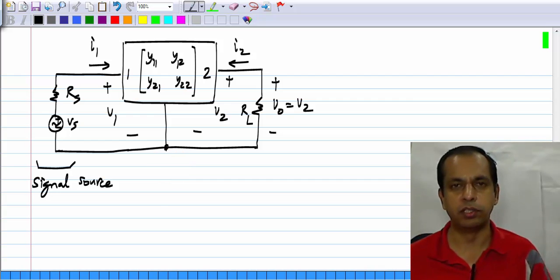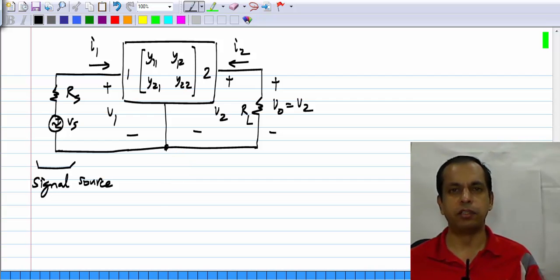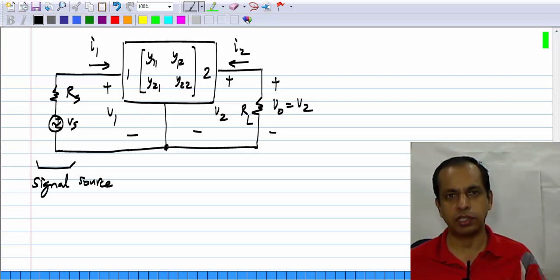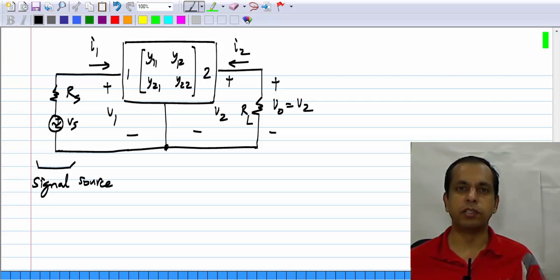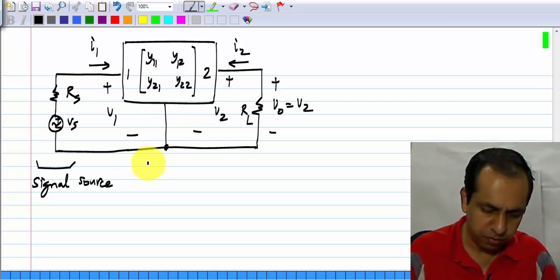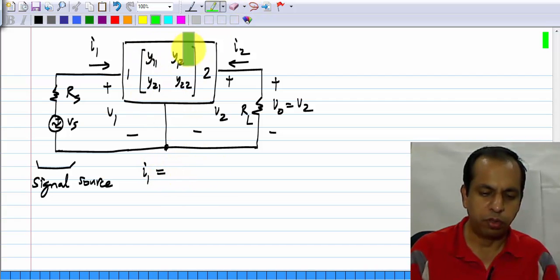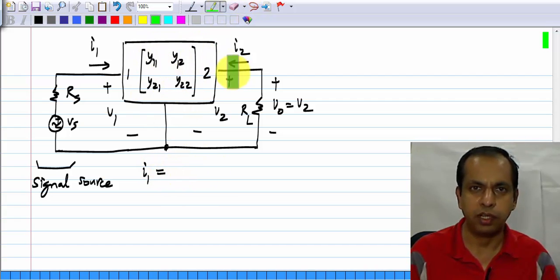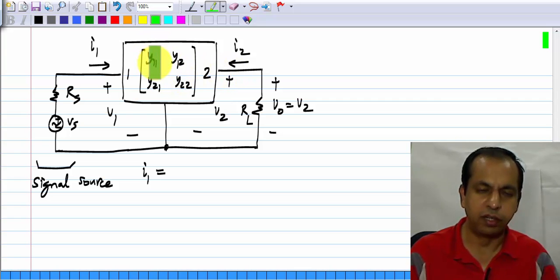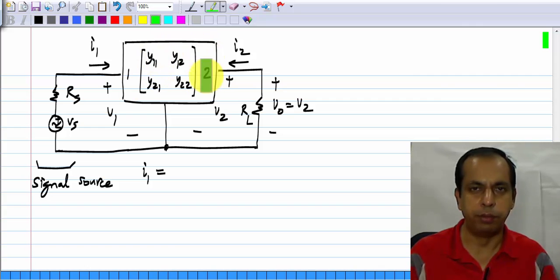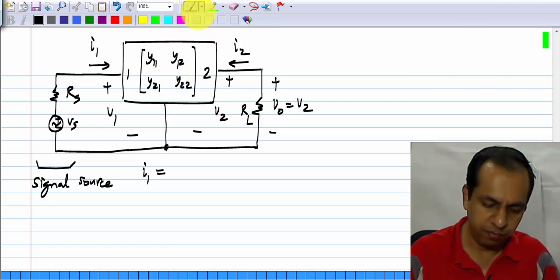This must be familiar to you from regular circuit analysis. Every element in the circuit imposes some constraints between its voltages and currents, and you take all of the constraints and solve for the circuit. This nonlinear two-port, by the way, I could also draw the small signal equivalent of this using conductances and control sources, that is the circuit equivalent of the Y parameters. So it will be the same thing.